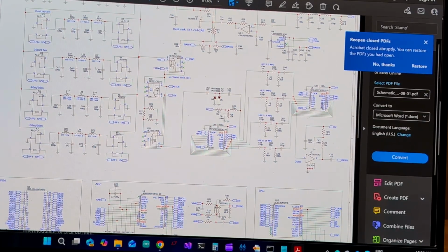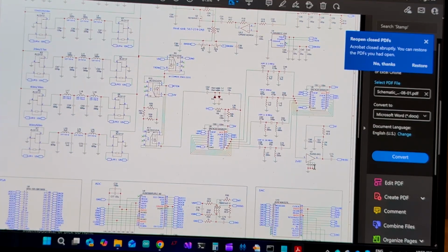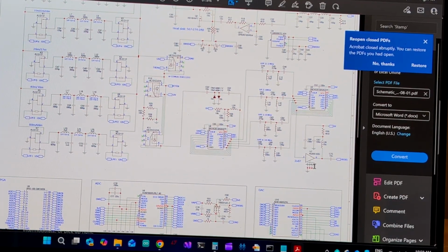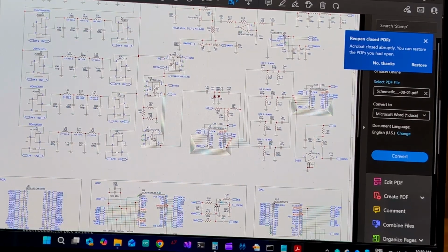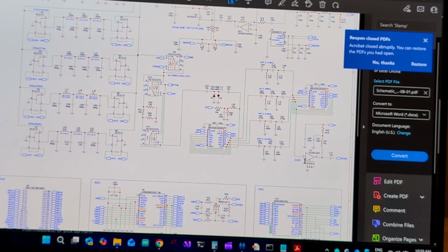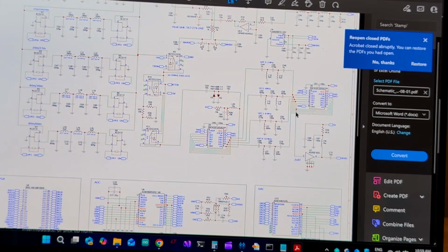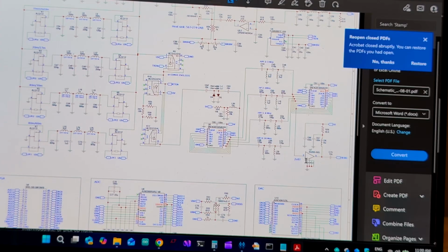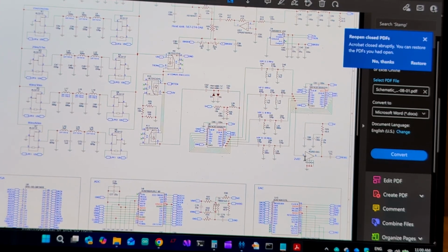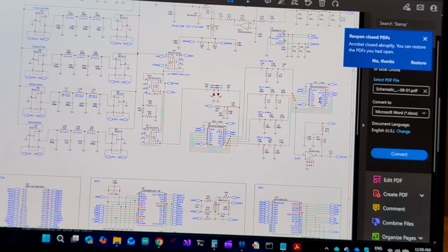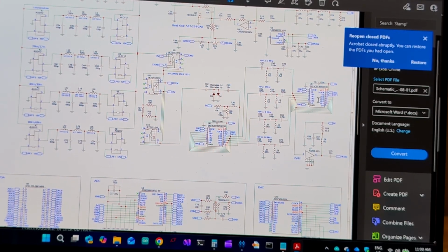And into another switching IC and into this is 20 dB of gain, and this is DC coupled to the switch to give the switch the bias it needs, and that's just fortuitous. The input to the MMIC is around 2.5 volts, which is perfect for biasing the filter switch.